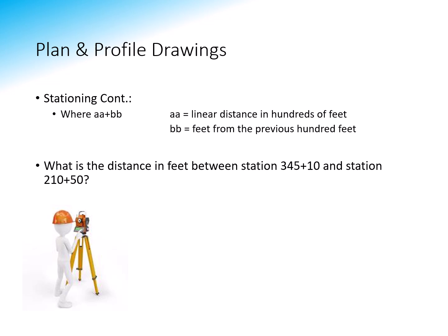So you remove that plus symbol from both of those, and then you're just subtracting the 21,050 feet from the 34,510 feet, which the answer would be 13,460 feet. However, you will probably be given this option, but the more correct answer would be 134+60. So just something to pay attention to.